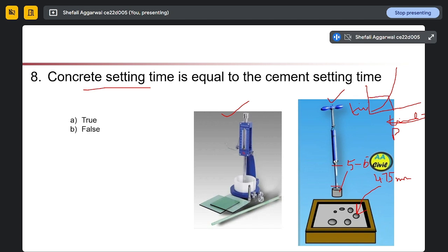See, does it act as a binding agent? No, the clinker is already formed. Strength of concrete? No, we are adding it in the manufacturing process of cement, so it cannot affect the properties of our concrete. Control the setting time of cement? No, because no water is added at this point, so we cannot say it is controlling the setting time of cement. As for controlling the rate of hardening of cement, so this is the correct answer.